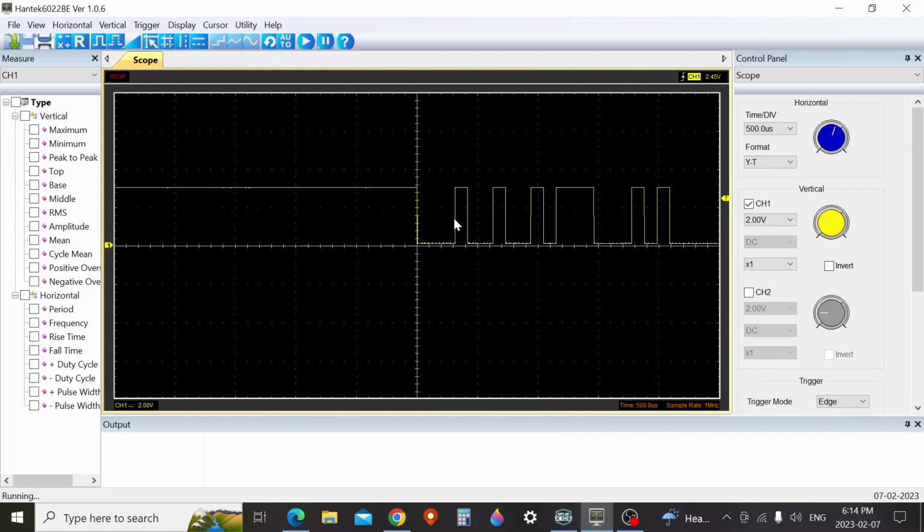So this here is 300 microseconds long. There's probably 3 clock pulses, therefore probably 3 lows, like 3 zeros, 1, 2, and 3 right there. So there's probably 3 zeros in there, and there's a 1 here, 1 high, and then 2 zeros here because it's only about 200 microseconds long, and then 1 because it's 100 microseconds there. And as you can see, we have maybe, is that 2 right there? Yeah, it's about 2 microseconds there. My oscilloscope is only under $100, and therefore it might not be deadly accurate on this content here.